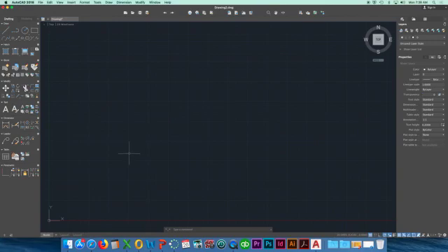So we're going to do drawing number 1, same thing that you did with the board drafting. You're going to use the line tool. You may start anywhere. You do not need to make a title frame or a layout sheet. So you choose where you want to start, and you want to go to the right 5 inches. So on the keyboard, just hit 5 and return. And it should make 5 inches. Then from this point, it goes up 3/4 of an inch, which is 0.75, and hit return.